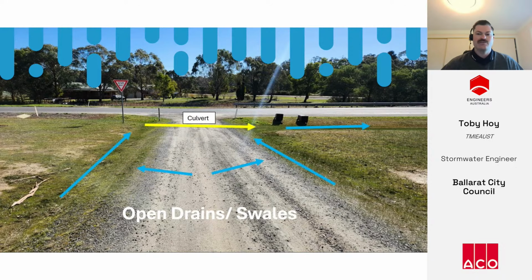Many open drains use alternative materials, such as brick or stones that have been split or cut. Ballarat was originally a gold rush town and still has many bluestone open drains that were constructed over 150 years ago. Another option regularly used, particularly for high flow areas, is to place loose beaching rocks in open drains to hold material in place and reduce the washout risk.